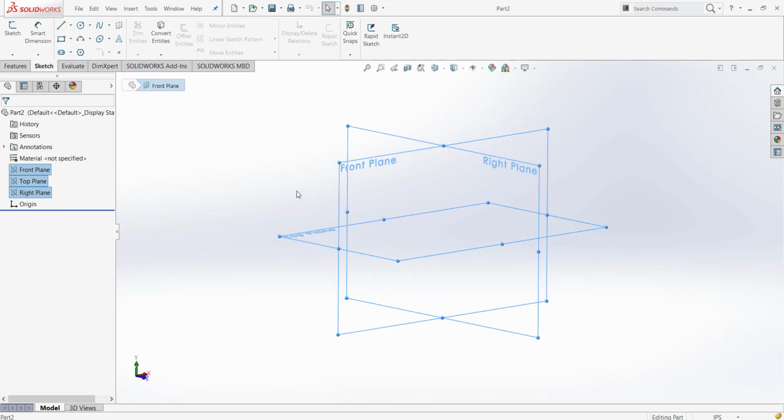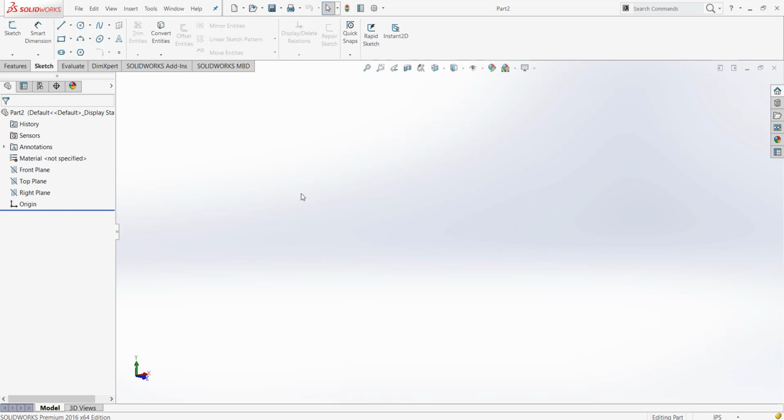The very first sketch you create when designing your part has to be based on what makes most sense when creating that component. For instance, if I'm modeling a coffee mug, it is essentially a hollowed out cylinder. So I would pick the top plane to create a circle. Then I would extrude that circle to create a cylinder. And then I would hollow out that cylinder to create essentially a cup or a mug. So that's what I'm going to do here.